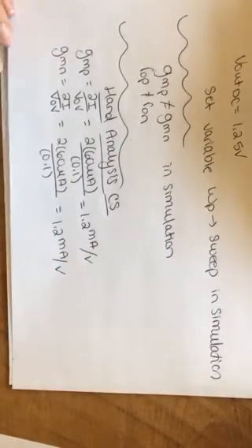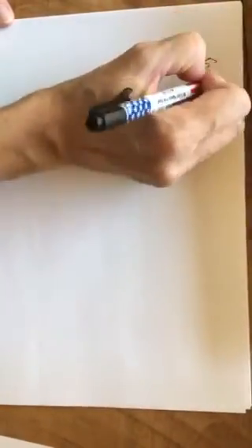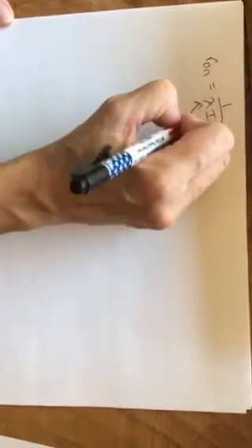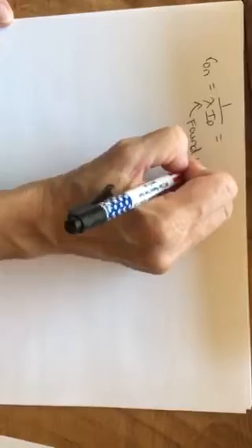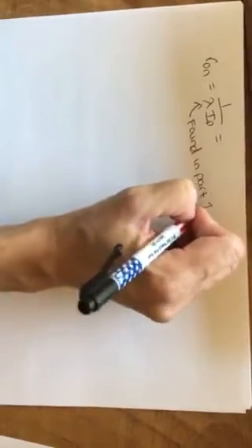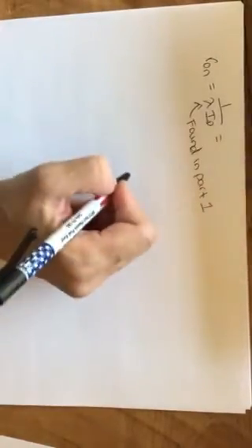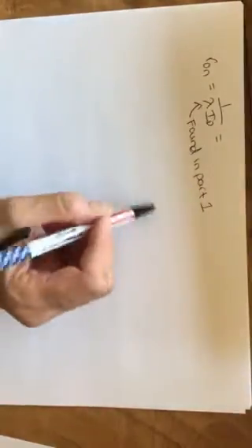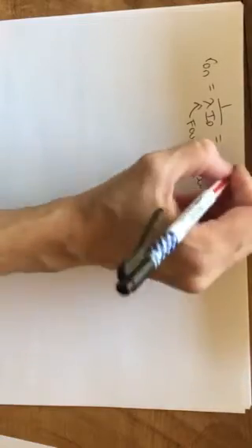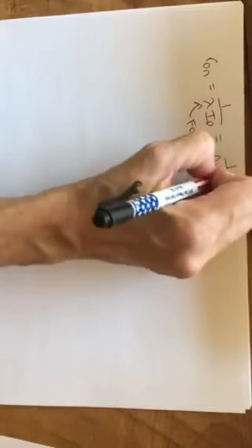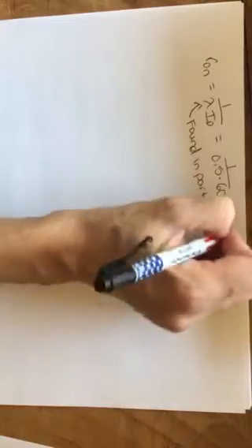I can also calculate the r naught of the devices through hand calculations. So my r naught of my NMOS device is 1 over lambda ID, where lambda is found in part 1. I'm making the assumption it's 0.5 just for sake of this discussion. So I can say it's 1 over 0.5, if I'd like, times my current, and you can find a number for that.